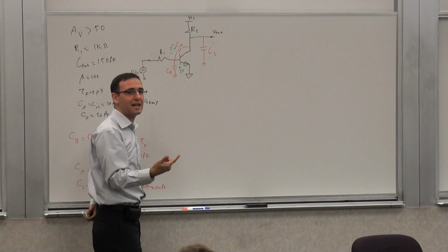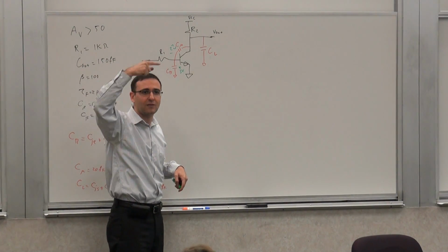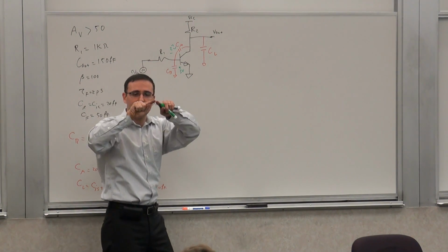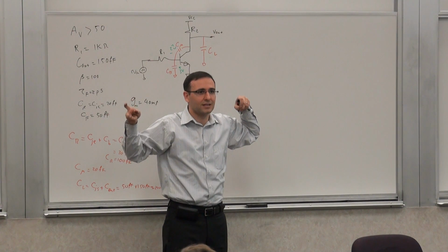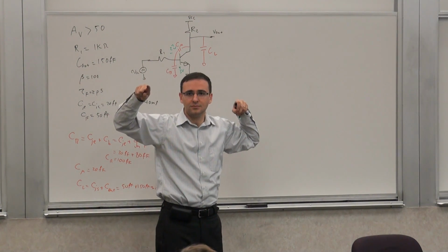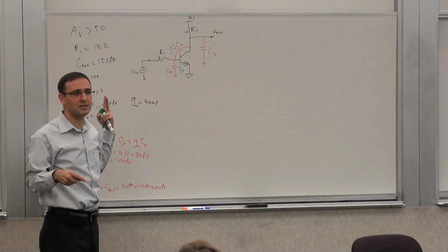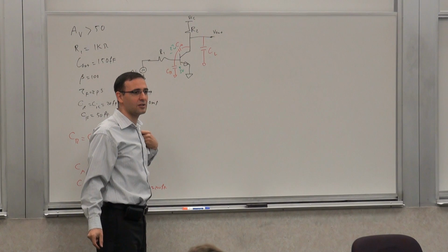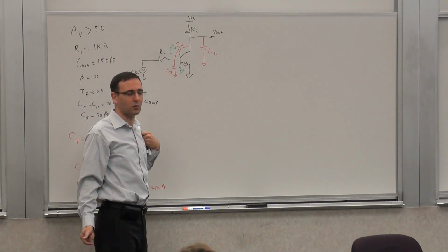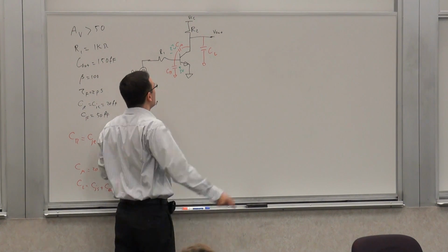Another way to see that is that you have a capacitive loop. If you have a loop consisting purely of capacitors, then if you determine the voltage on n-1 of them, the nth capacitor voltage is already determined, by KVL. So how many zeros? If I short circuit this one, would I get a non-zero transfer function? No. If I short circuit this one, would I get a non-zero transfer function? No.